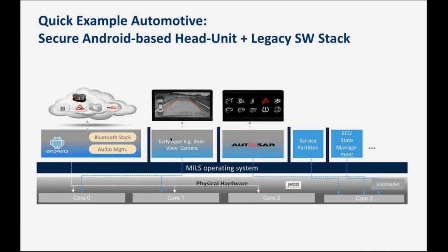You might have safety critical needs here running in classic AUTOSAR to manage your cluster or other things that have safety requirements, unlike the Android part, which probably does not need any safety certification in such a system. And you have several other partitions that you would need to provide specific services or other monitoring functions to maybe check the state of the ECU and other things. So here you already see that we have many different types of applications that we want to somehow run on the same system.